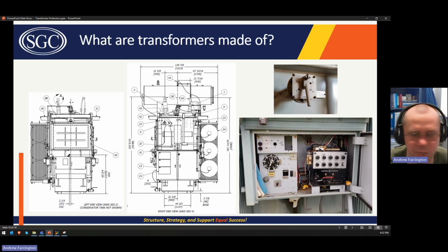So this seems like they did a pretty good job of setting the de-energized tap changer position such that the LTC operates around neutral. But that's how you'd tell.